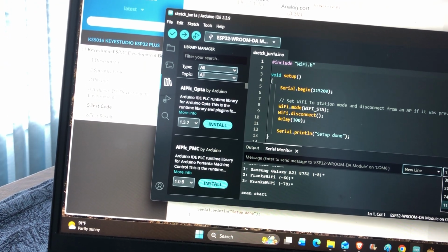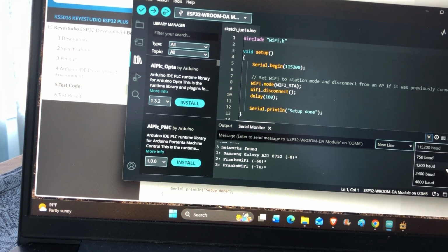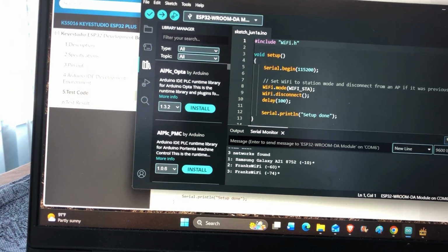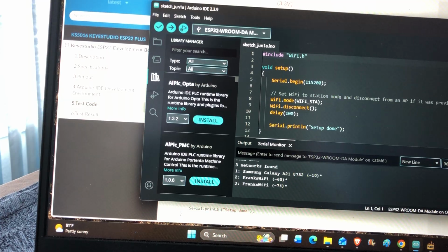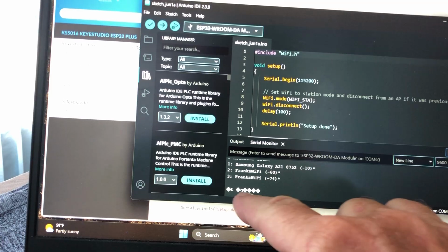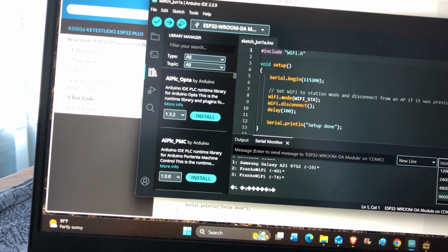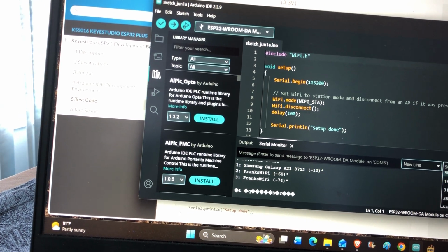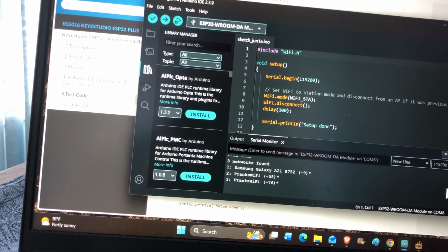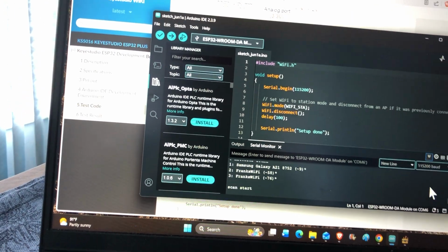If you leave this at the default of 9600, you get a readout that's not legible. So you'll want to go to what's stated in your sketch, and then you get a readout that's legible. There'll be more about all this.